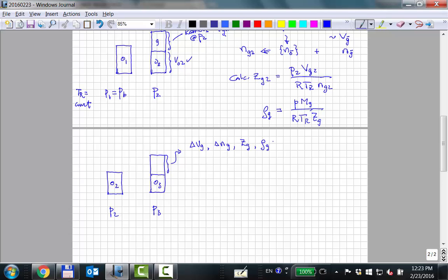And then I told you that we needed the gas viscosity, and that's not measured directly, but the viscosity of gas is usually calculated at each stage. And it's calculated from a correlation, typically a correlation that's a function of gas density I believe, and reservoir temperature. And this correlation is called the Lee-Gonzalez, and I believe it's given in Chapter 3.